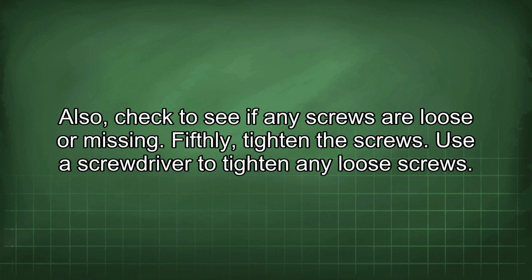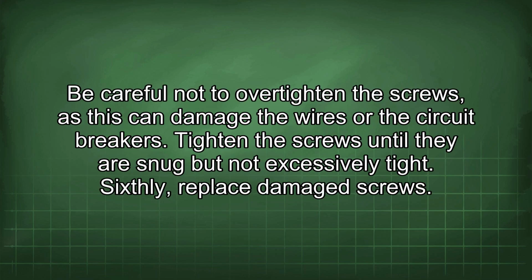Fifthly, tighten the screws. Use the screwdriver to tighten any loose screws. Be careful not to over-tighten the screws, as this can damage the wires or the circuit breakers. Tighten the screws until they are snug, but not excessively tight.